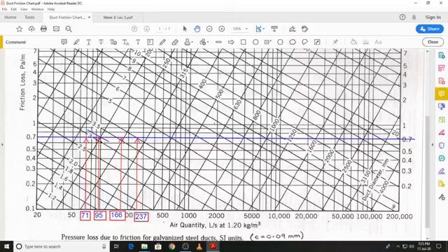And now that completes our column for the velocity. The remaining calculation is straightforward. You find out the area, and based on that area you find out the diameter or the duct sizes for each of the 5 segments. Once we have got that information, we proceed to find out the pressure drops in the runs and identify the index run.